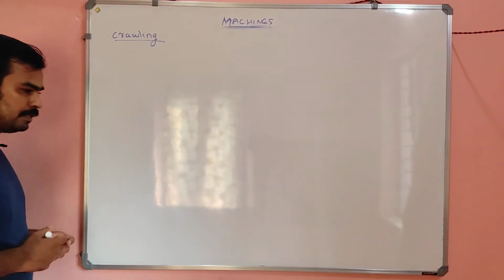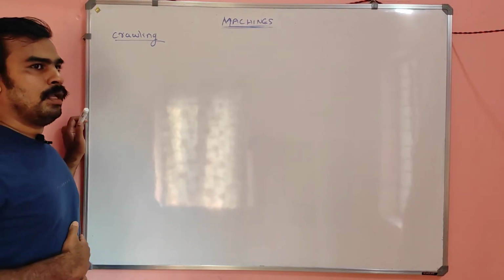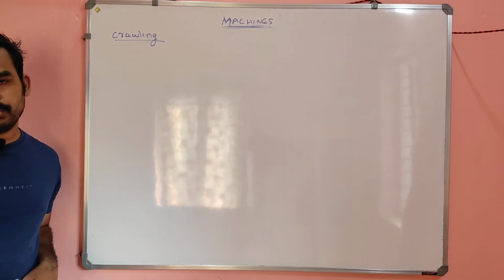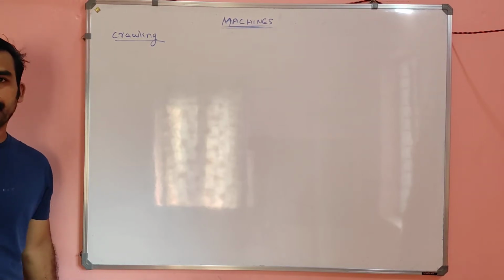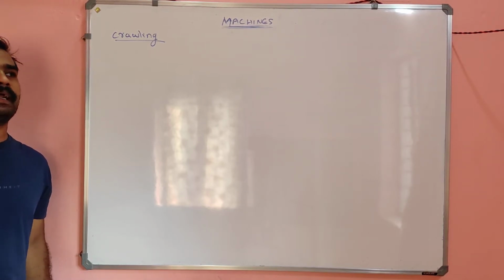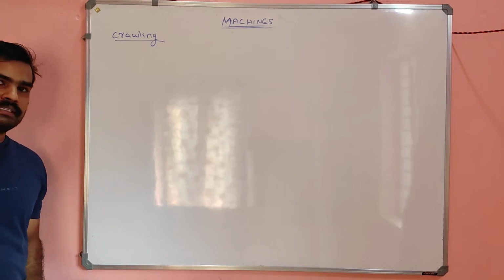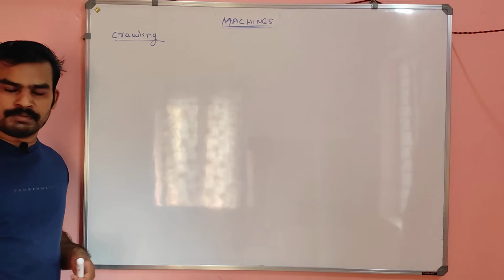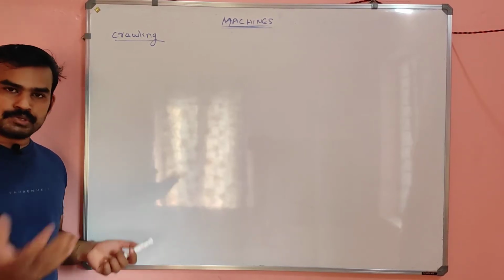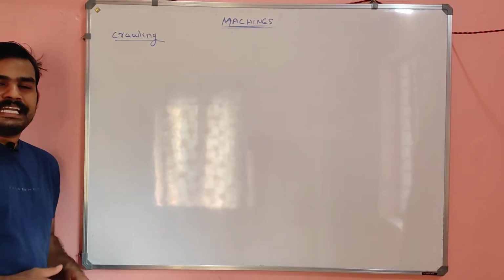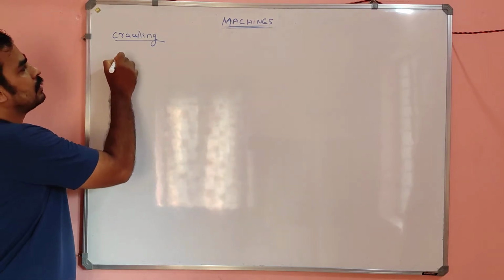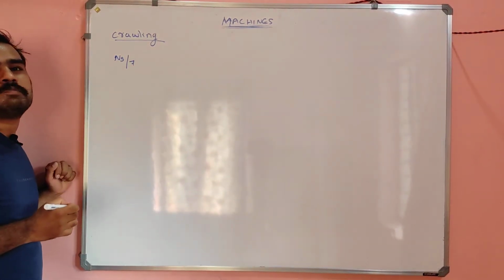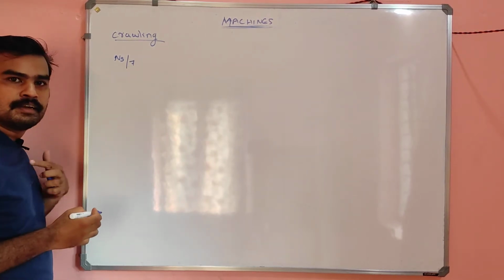Crawling is nothing but an effect due to the harmonics in the supply. The motor will not pick up to full speed, that is the synchronous speed, or near to synchronous speed, as soon as we switch on the supply, but it will crawl at a speed of 1/7.